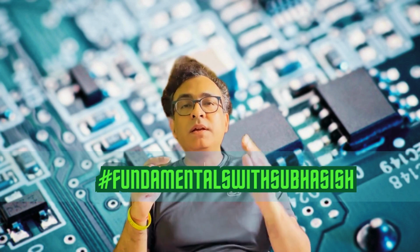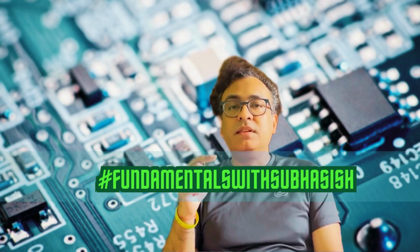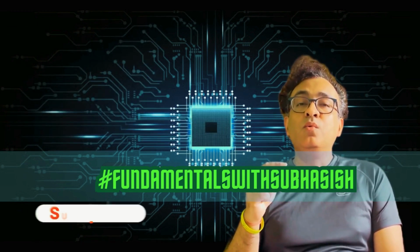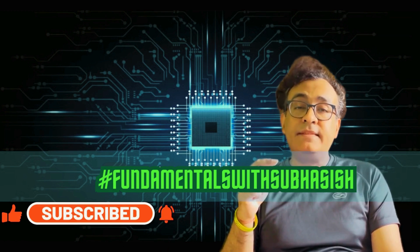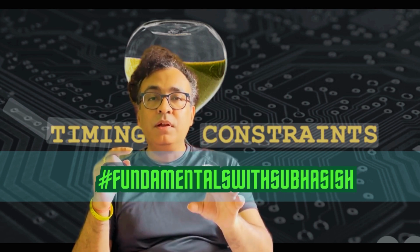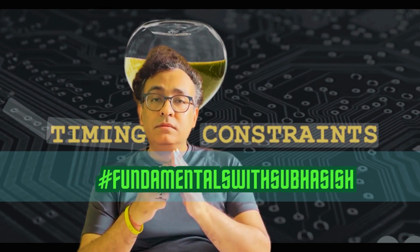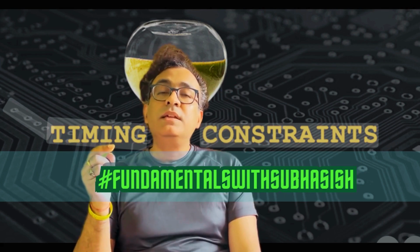Now, when we convert this functional specification and integrate it into the design process itself, we do it with the help of design constraints. A design constraint is a kind of syntax by which we write this specification. For example, if I have 2 clocks and I know that these 2 clocks are asynchronous to each other, I will write those 2 clocks in 2 different groups. I will also write what clock frequency I am expecting in this chip. And if I know the total time required from input to output, I can write that information also. But those things are more in detail.